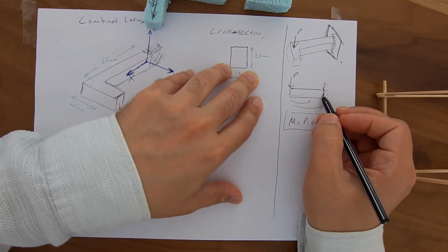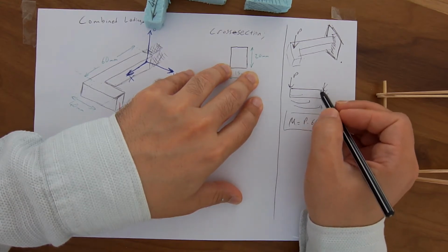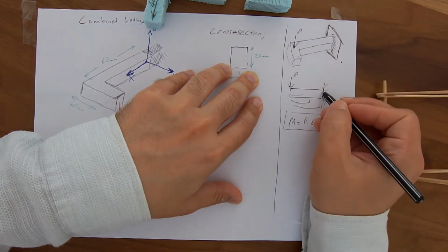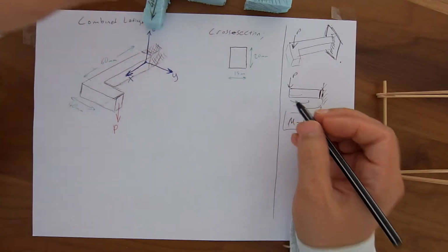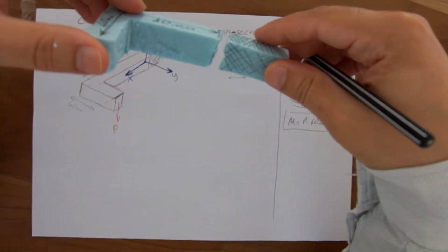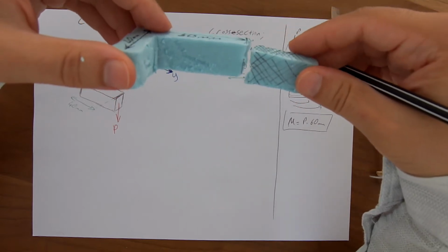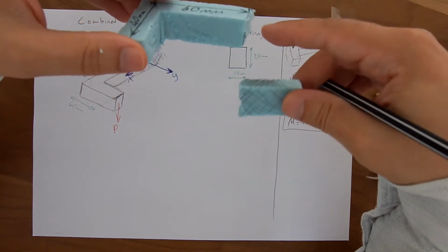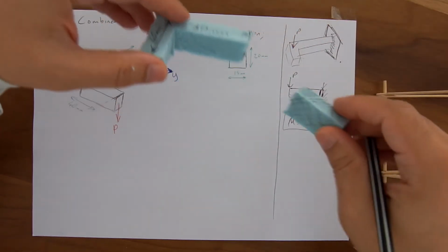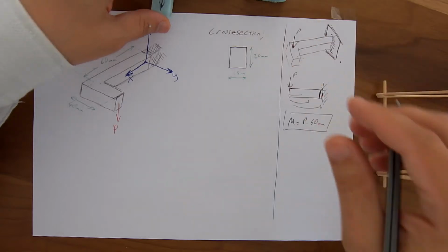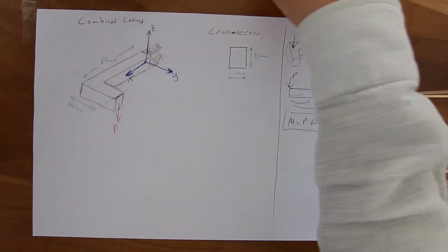What else is there? There is also transverse shear happening in the cross section. Some bending moment and transverse shear. And this failed mostly due to the bending loading. There is a little effect of the shear stress, but the majority of the failure is caused by the bending stress. We discussed this in the previous lessons. Okay, now going to the other rod,